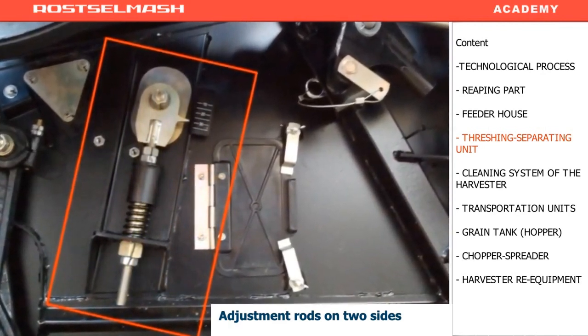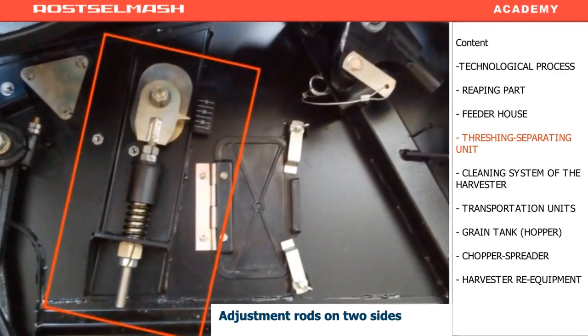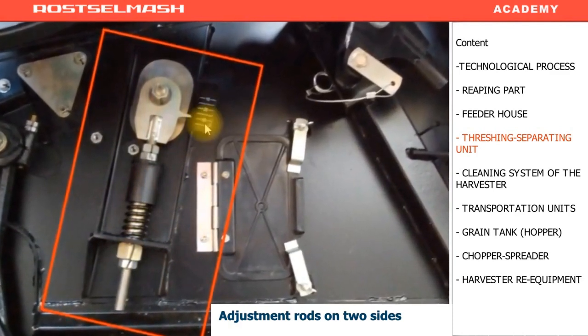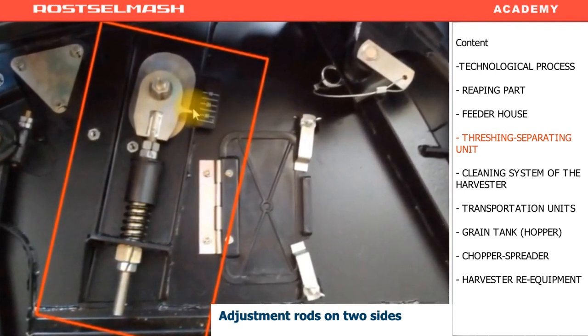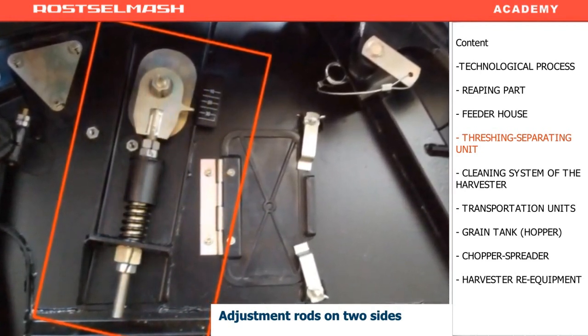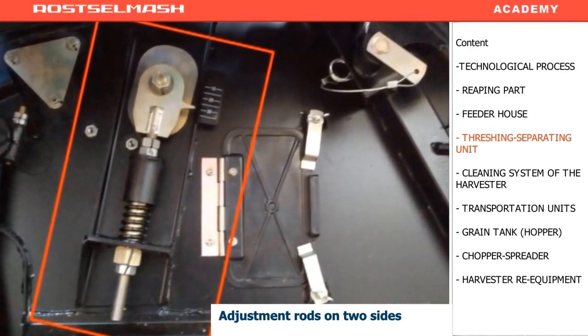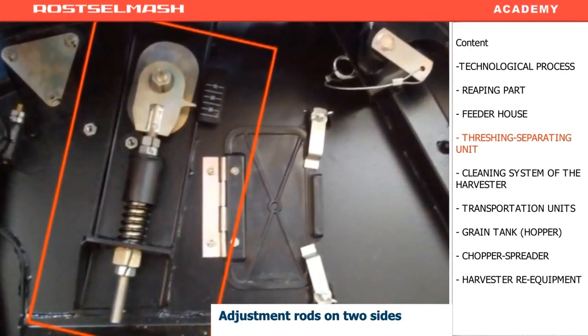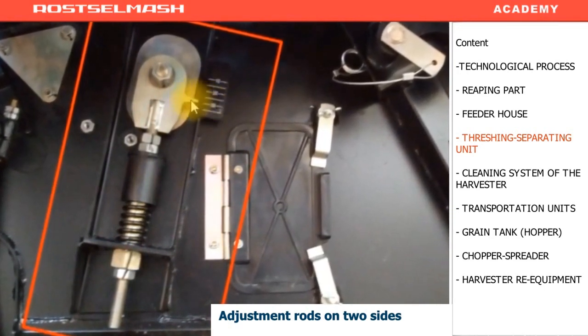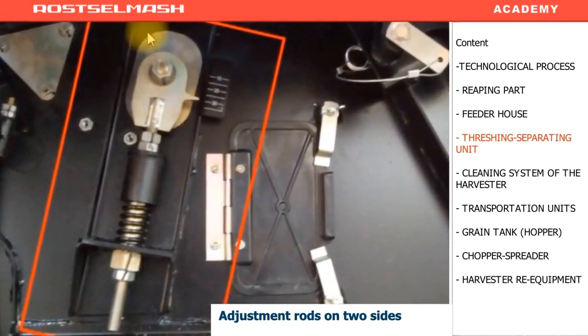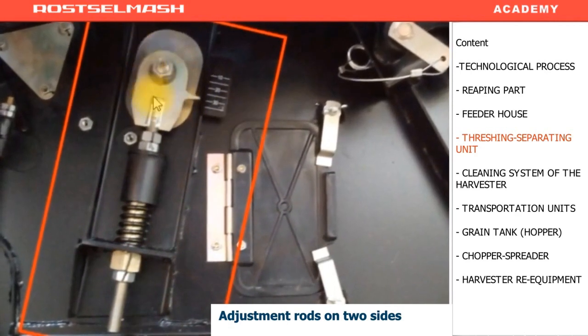A frequent mistake every time there is clogging. One might think that the only reason of clogging is small clearance, but this is wrong. It works in a different way on the beater. When there is too much straw and the clearance is too big, the falling straw gets stuck on the concave and starts clogging it.